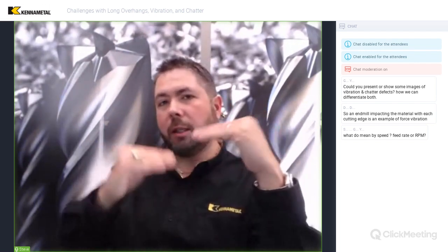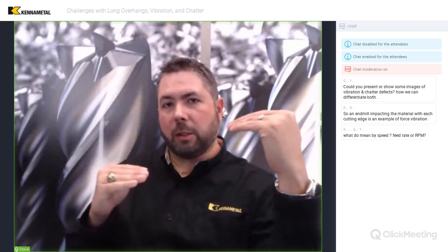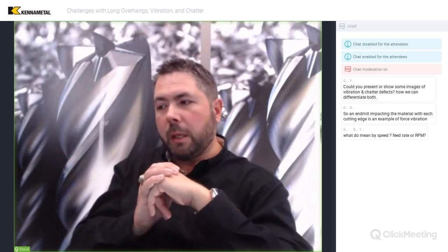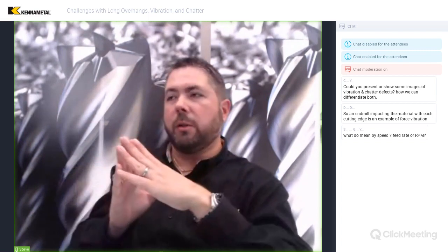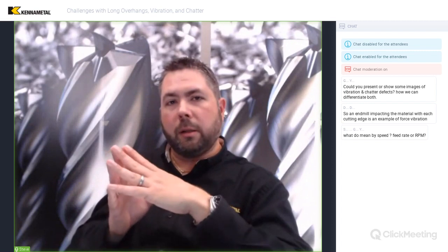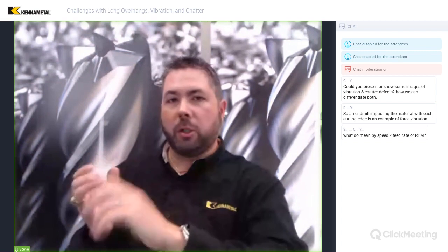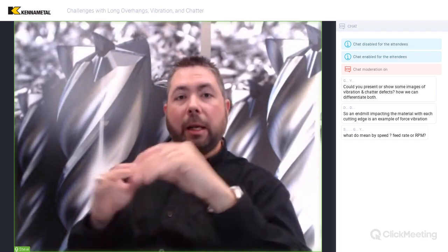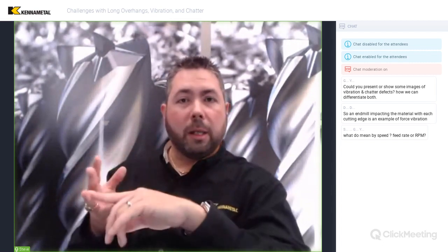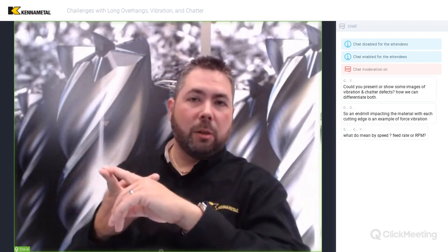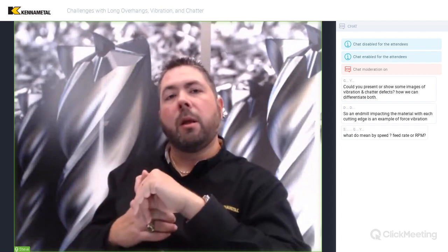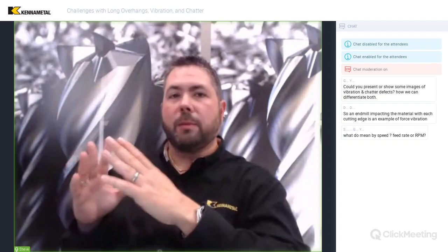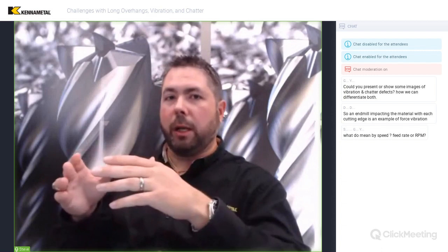If those chip thicknesses are constantly changing up and down, we've created a periodic force coming in and out that's always given us issues, right? So we've got an impulse, then we've got self-excited chatter after that. However, if we can keep that a little bit more constant, things start to get a lot better. So in milling, our approach is normally to think about conditions that will keep us out of the range of chatter, and tool geometries that make it easier by making a bigger sweet spot. With unequal index tools, variable helix tools, and relief styles on our end mills to add more process damping, all those things make that a broader range that you can work in, okay? But that's the goal: to stay as matched up as you possibly can and then widen those sweet spots as much as you can as well.